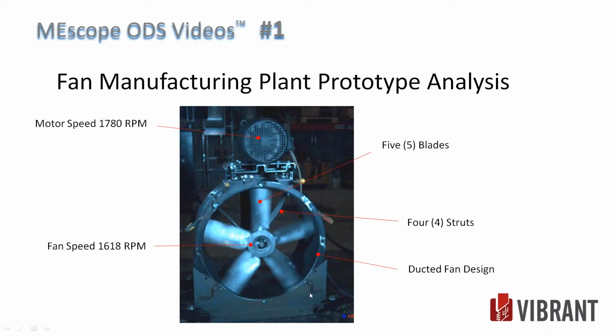So there's an unusual interaction. It's a ducted fan, so there is going to be some duct that's connected here and on the other side. But what's tricky about a ducted fan like this is the clearance of the blades. If you don't make the ductings up properly, you'll put a twist into the structure and a blade will rub, and it gets a little tricky. You want to have as tight a clearance as possible for performance, but at the same time you don't want it to rub.